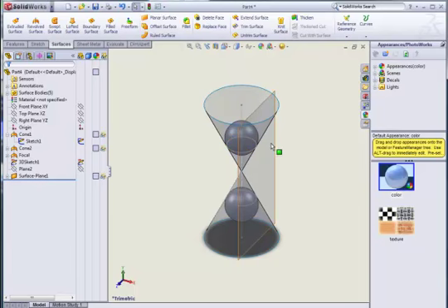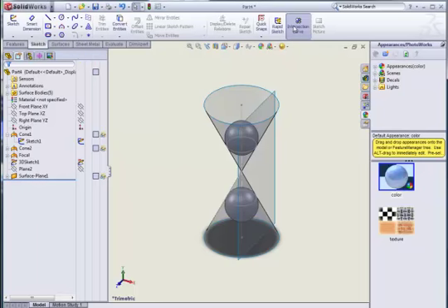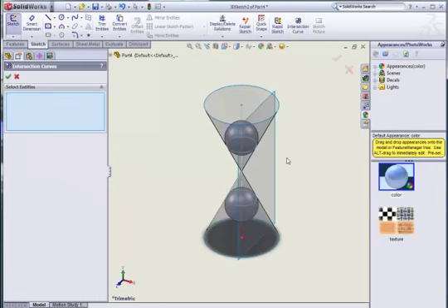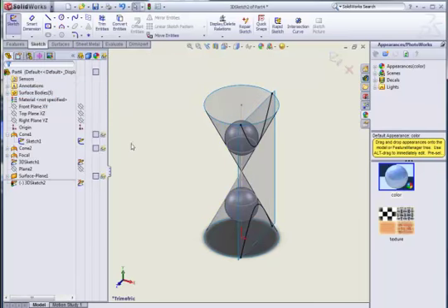So to show them, again we go to our sketch tab and intersection curve. So the surfaces that will be intersecting to give us our hyperbola are our double cones and our cutting plane. So click OK, and there you can see our double hyperbola.